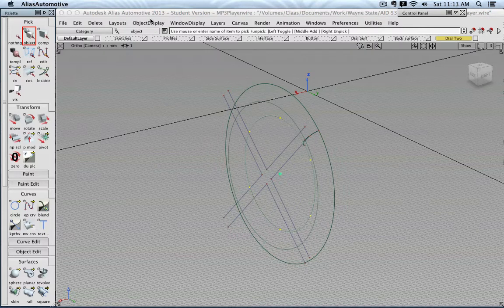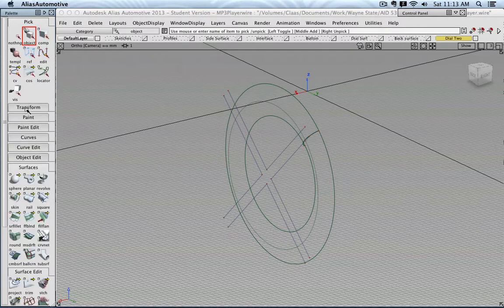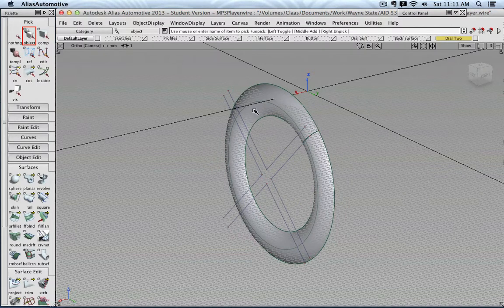You see that they might be good as a visual indicator, but you don't really need them for working, because in Alias 2011, the multi-surface draft tool only works on surfaces, but by having created this button arc top surface, we now have a surface where we could sample the edges from.